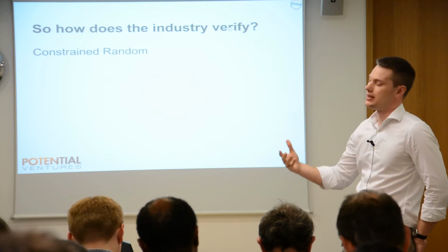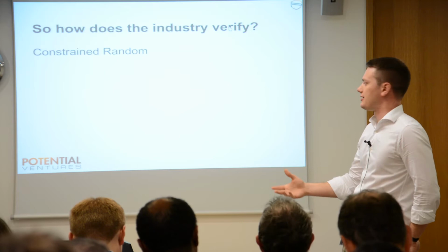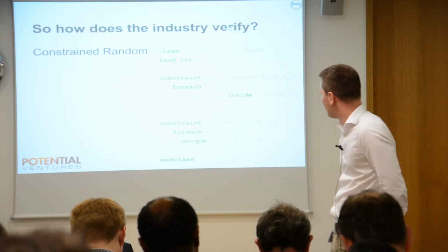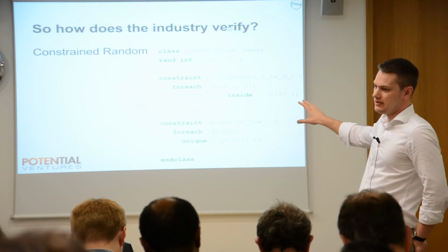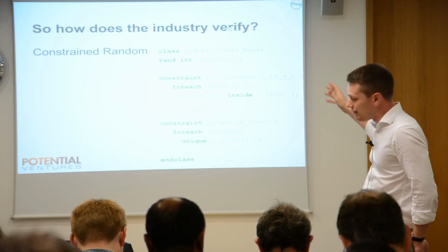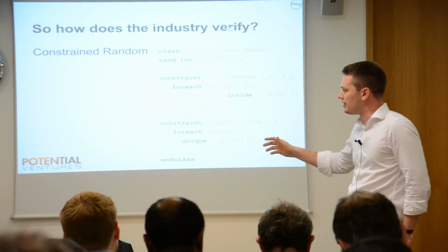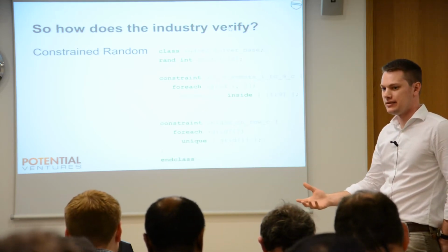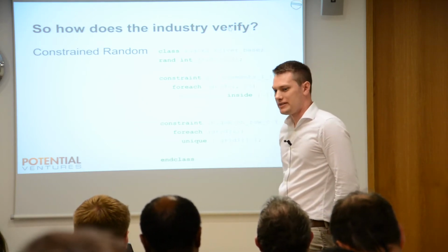We use a constraint solver to solve that problem, and it generates stimulus that exercises our design. A classic example of that would be Sudoku, where we can describe the problem as a set of constraints that have to be satisfied, effectively the rules of the game. We throw CPU power at it, and it can solve Sudoku for us. We can do the same thing with our tests. We can describe what valid inputs are for the different interfaces, throw CPU power at it, and it writes tests for us effectively.